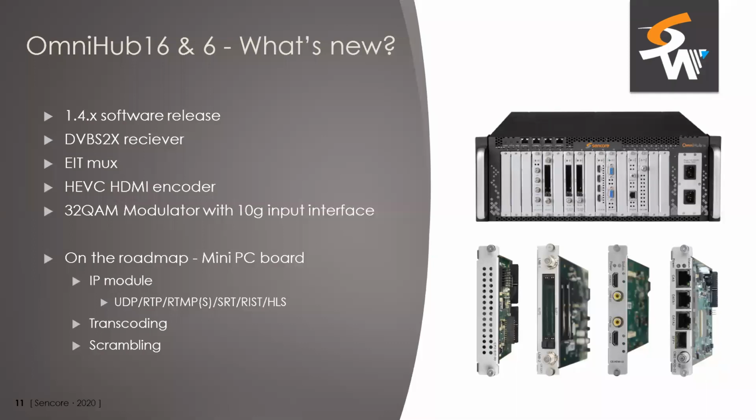And the last new model, which should be released somewhere next month, is a very dense 32 QAM modulator, which will be able to receive IP input signals directly via a built-in IP port. So the model can receive signals which are not going through the chassis, and take them directly from the data switch. The model will be equipped with 2 gigabit ports for traffic processing, one for further scrambling system integration, and also an SFP port, where we'll be able to place a 10 gig SFP. So a very powerful model for dense cable applications.